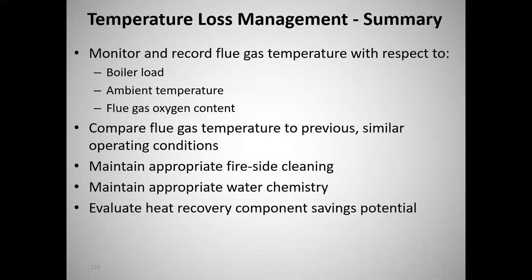Compare flue gas temperature to previous similar operating conditions. But you've got to get the parameters, the ambient temperature, the load, and the flue gas oxygen content, to have been in a similar range to do a fair comparison. Maintain appropriate fireside cleaning, maintain appropriate water chemistry, and evaluate heat recovery component savings potential. And we will get into that. We'll use the measure tool to do that for us.